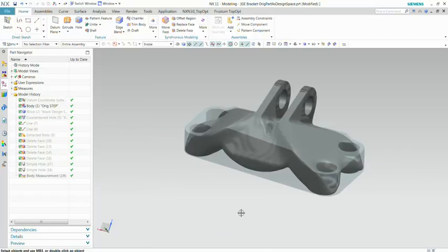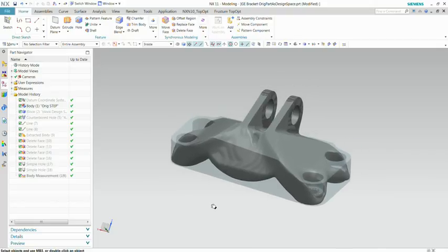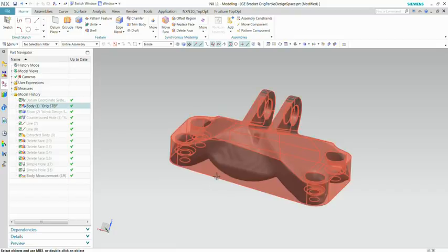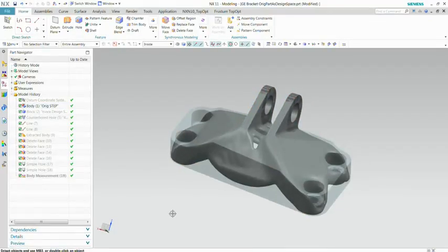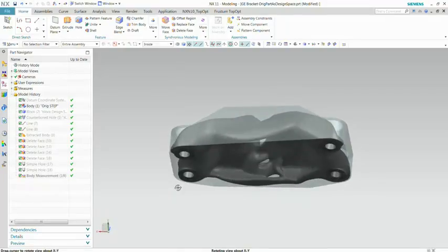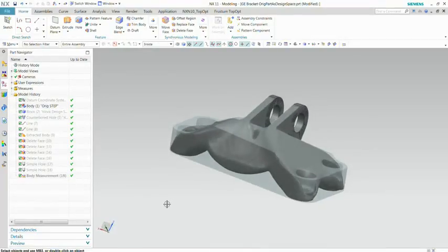Another example of an optimization is, for example, this bracket. It was used for a contest on topology a few years ago, but here you see, for example, the design shape of a volume where we allow to have material, and you see here inside the optimized shape of, for example, this bracket. So it's a method that gives you, in a very fast way, already some shapes that can inspire you for your final product. And because of the precision of the result, maybe it's already good enough for direct production purposes.